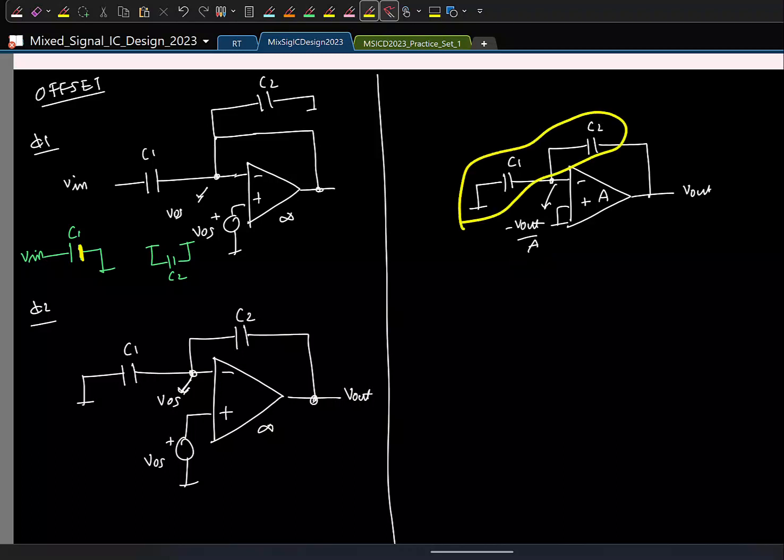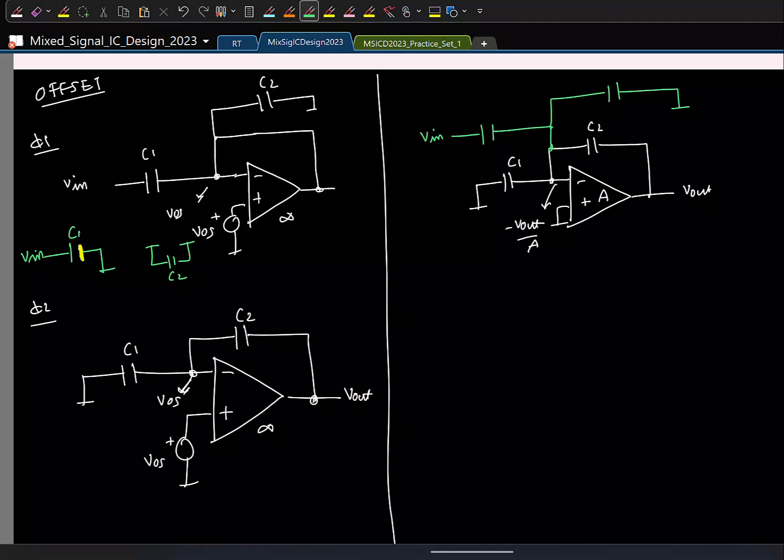Now which means I need to take another capacitor, charge it to V in with respect to this voltage, another capacitor C2, discharge it to ground with respect to that voltage. The logic is same. I want to obtain this error voltage and then do this thing. For an offset case, it's simple, but this circuit will solve both the problems to some extent, yes.